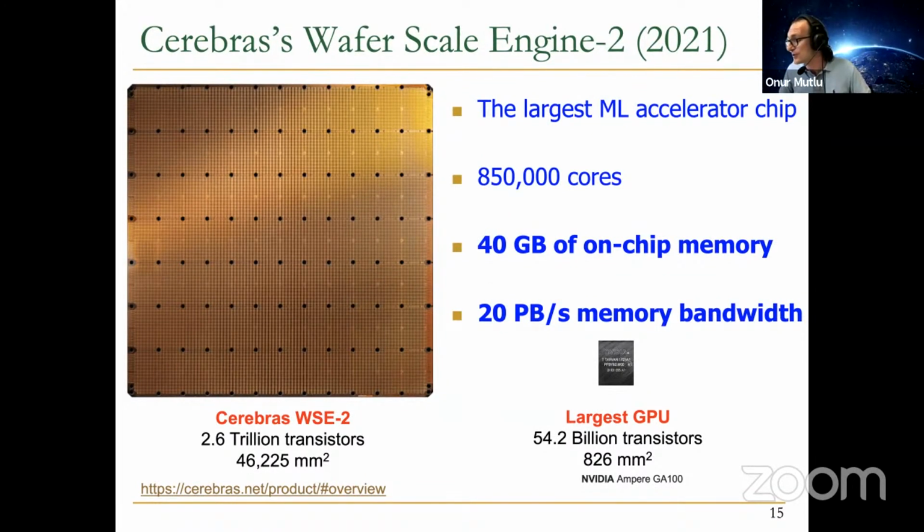There's one question: could you go 3D once you run out of 2D space to uphold Moore's law? So absolutely, and people are trying three-dimensional integration. I mentioned this maybe in one of the first lectures, but certainly three-dimensional integration is one way to scale your computation and memory. And people are doing a lot of work in that right now. High bandwidth memory is, for example, today 2.5 dimensional, but it's going to be three-dimensional in the future. And there's a lot of work on getting monolithic three-dimensional integration of different layers.